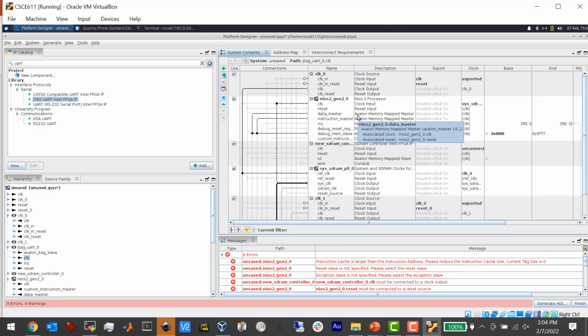Now, there's also a reset input, which is going to be connected to one of the switches or the buttons on the board. You see there's a clock in reset, which has an input export called reset. So that's the pin, and the corresponding output for that is called clock reset. And we're just going to use the raw reset directly from the switch to reset all our stuff. You might say, well, wait, isn't that dangerous? I mean, that button needs to be debounced, right? You're going to push it and it's going to be bouncing around and stuff? Yeah, seems to work though for us.